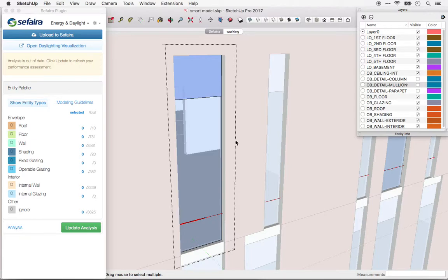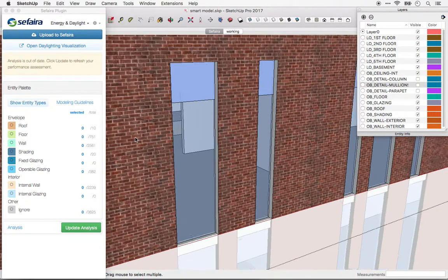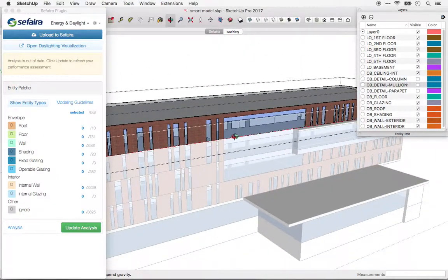And then the mullion just sits directly on top of that glass. I can do that because the properties of the window, like the U factor, already take into account the window frames and the window mullions, because what we're looking for in that input is an overall assembly U value for the window. I use a similar strategy for curtain walls.